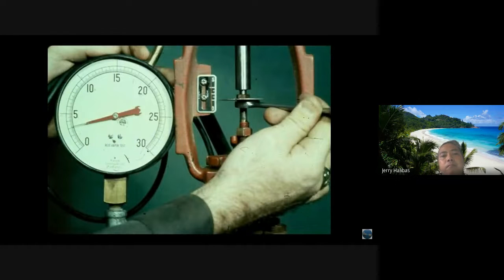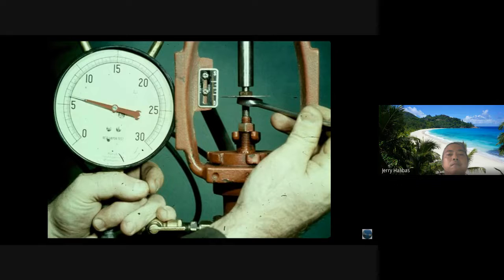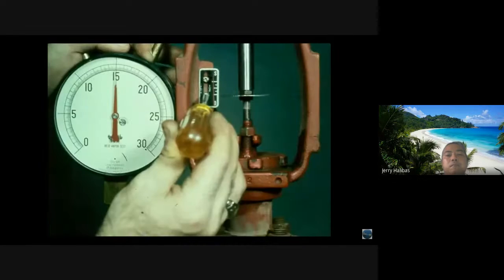We will check this valve first. It is a 3 to 15 psi air to open valve. Apply 3 psi. Make sure the plug is just touching the seat by loosening and turning the plug stem. Apply greater than 3 psi. Then screw the plug stem into the actuator stem 2 more revolutions. The extra 2 turns will ensure that the valve seats solidly. Lock the stem lock nuts. Apply 15 psi. Make sure the valve has full travel. Adjust the travel indicator if it doesn't agree with the indicator disc.